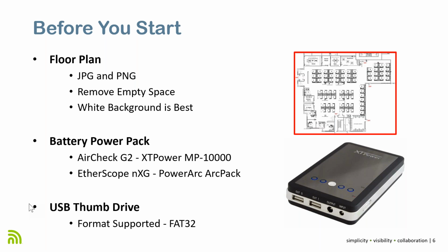Still, if you decide to use a thumb drive to transfer the floor plan into your unit, notice that at this time, the format that's supported is FAT32. So make sure that before you try importing a floor plan, your thumb drive is using the right format, else the unit will not see the floor plan in there.